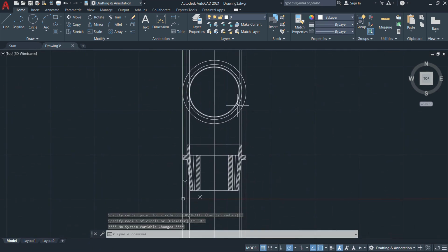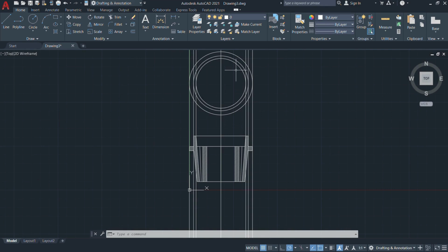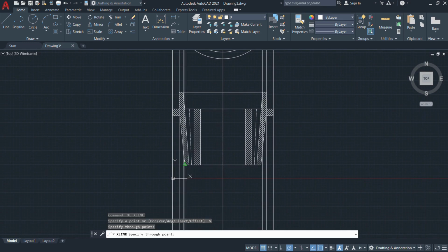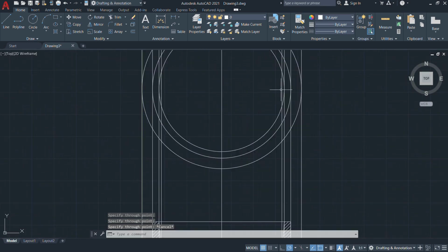Again type the command Xline. Then same as before, use a vertical line to choose the reference of our bottom point. Because it is a tapered portion, not a cylindrical zone, like a conical section, you need to represent the bottom portions also. So select two opposite bottom points and use a circular profile to draw from the center point up to the reference.